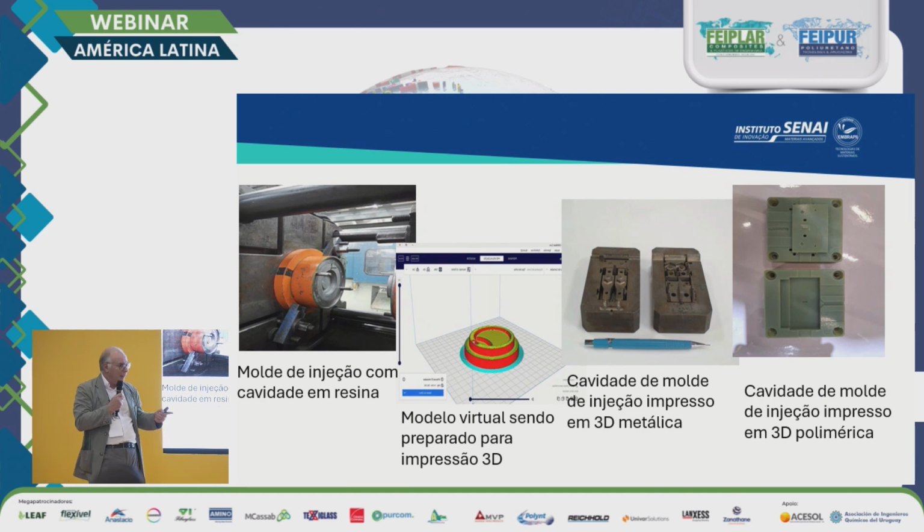Well, if I don't have a cooling system. Well, what do we do with the mold? You take the steel block, you mill it, you drill it. So in this 3D printing process, you may have your cavity, and then the cooling channel can go along the cavity. That's what I can do. What's the advantage? I may have smaller cycles because my cooling system will be more efficient, okay?